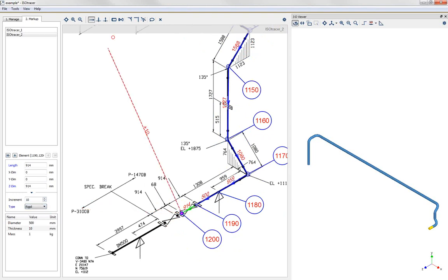Note that there's also a short key. You can use the short key P if you want to select piping, and the short key R if you want to select rigid. Okay, so then a short element of 6/8 and another rigid of 1/4. Okay, so these are all rigids. Now I select P, that's the piping system, and I continue to the end.